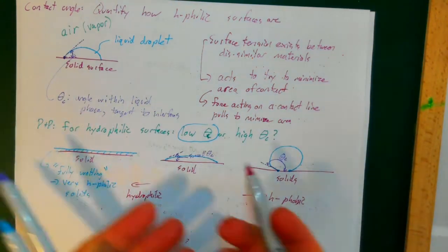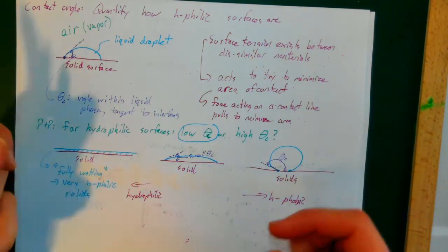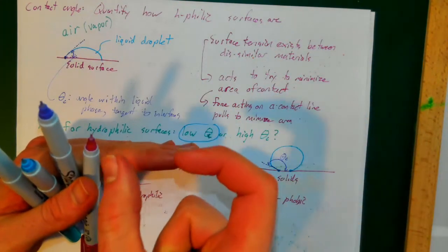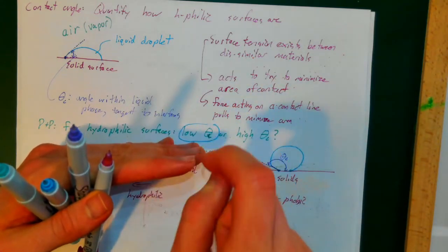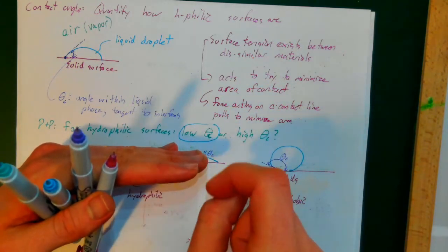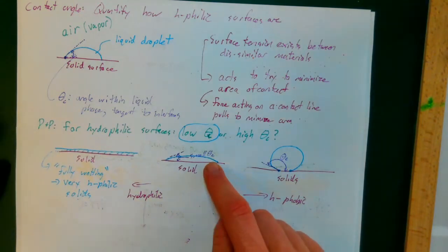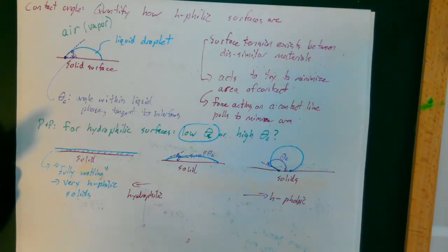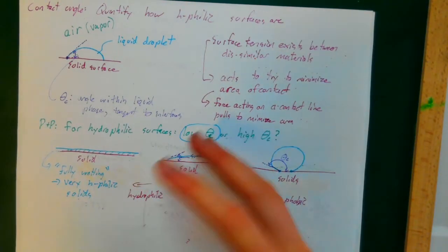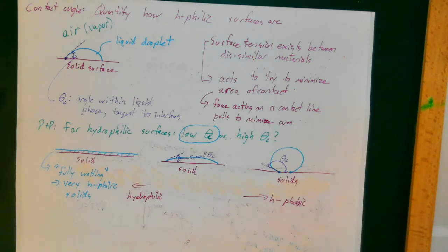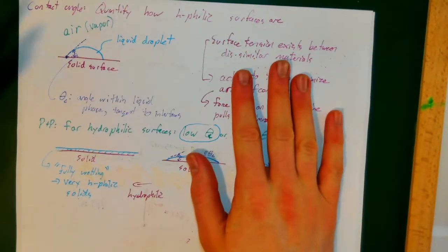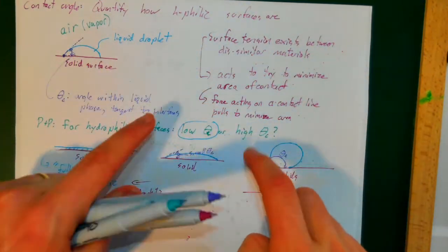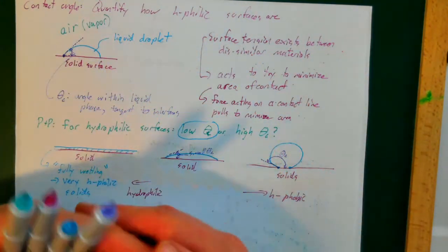And this is something you can observe experimentally. You can take your surface, put a droplet on it, get a macro lens or a microscope or something like that, and zoom way into the edge of the droplet, take a picture, do some image processing, or even just take out a protractor and measure these contact angles. And that gives you a metric of how hydrophilic or hydrophobic it is. Of course, you don't even need to do it yourself. A lot of people have already done this for common materials, so you can just Google online contact angle for many common materials, and you can look them up.